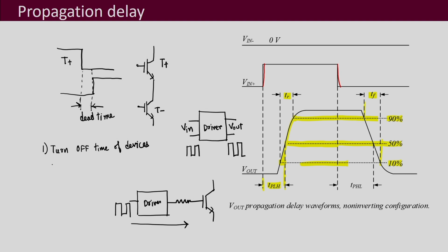So, that is why the propagation delay of the driver is what you should be looking into before you decide your dead time for your circuit.